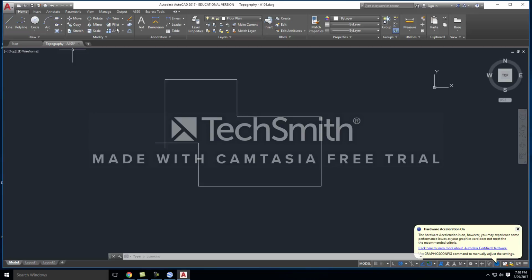Or on the board. We're going to learn what fillet is typically used for, and also the cheating way that a lot of people actually use it. Typically, let's say you're designing a parking lot, where you have lots of radiuses, lots of big arcs that you're working with. Well, you might have a line that looks something like that, and a line that looks something like that. What fillet does is you select your two lines and it puts a nice perfect radius on there for you, okay? So let's look at how to use that.